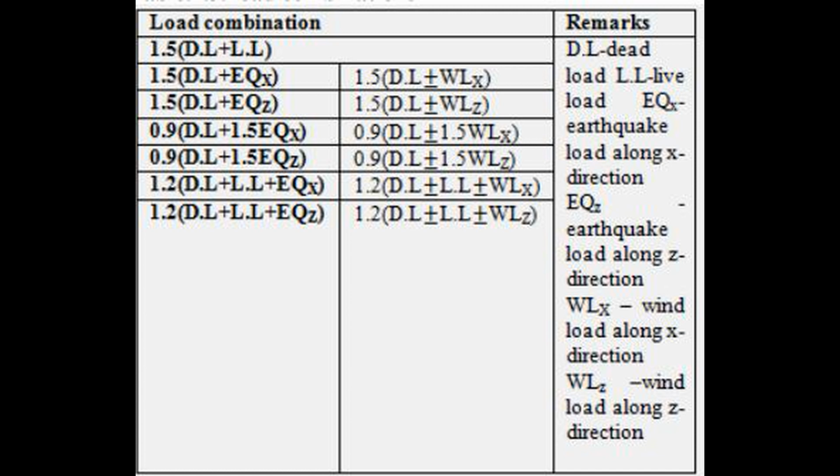Therefore, a masonry block wall is required to be designed for dead load, live load, and wind load. For an 8 feet high wall, earthquake loading is not required. The typical design life should be 50 years.